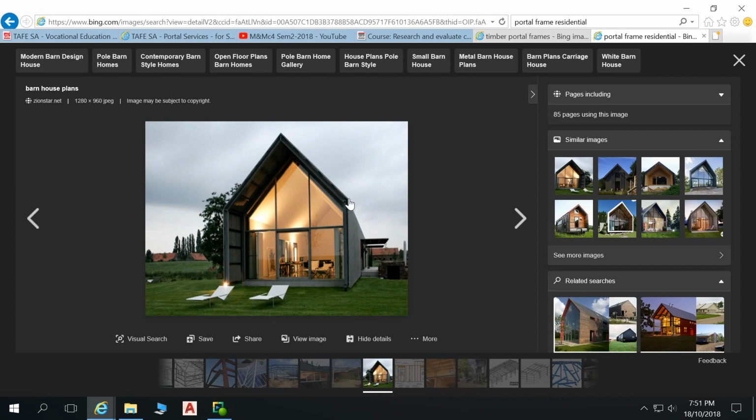Like, you've got a funny detail here, so there's possibly no gutters in that, because they'd have to hide their gutters inside their portal frames. It's not going to happen. Oh, yeah, no, in all reality, it's not going to happen. So probably don't have gutters happening on this. You could run gutters between your portal frames and run your downpipes within your wall cavity to create something like that if you wanted to have gutters on it. But in all reality, they're probably not using gutters on this.